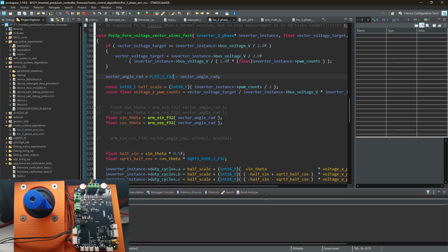Looks nice. I'm glad that yesterday on stream we found the flag that allows the compiler to show us warnings when it detects that we are using double. Because in embedded systems we would want to never actually use double unless you have a very good reason to do so. Because most controllers don't support it in hardware, only in software, and software floating point calculations are very slow. So don't do it. Don't be like me.